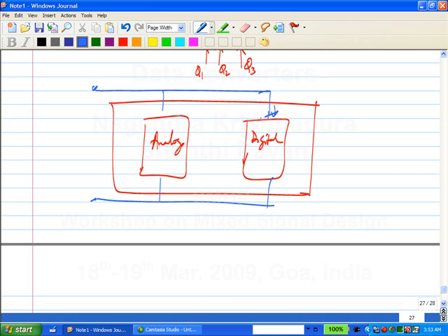Huge spikes at what, I mean, every time, or are there some times when the spikes become particularly large? So if you use standard CMOS logic, there is in fact no current at all, or there's leakage current, which is a small DC component at all times, right? And during clock transitions or switching transitions, there will be huge spikes of current.